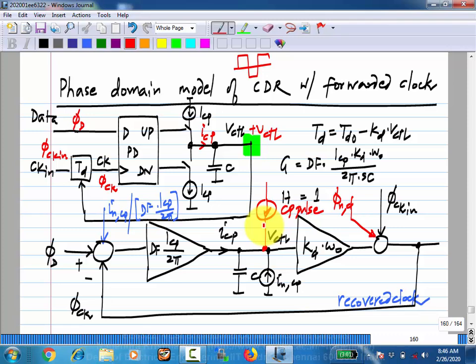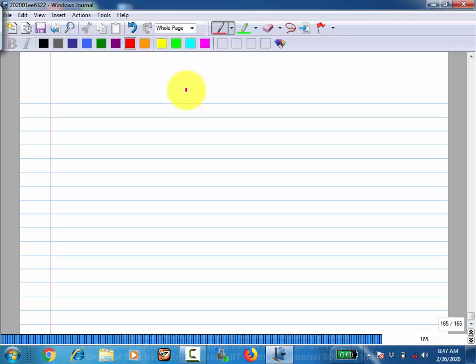You can, right? If this TD is only discretely variable, then the model may also capture that. On the other hand, it depends on how you make the delay line. Let's say you make an inverter chain and vary the supply. In this case, the delay will vary continuously. Of course, you cannot go below a certain value in a given process, but it does vary continuously.